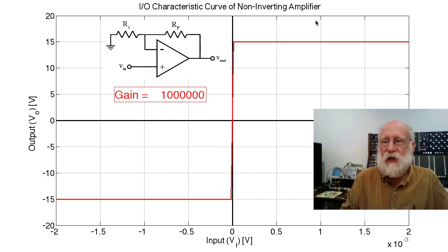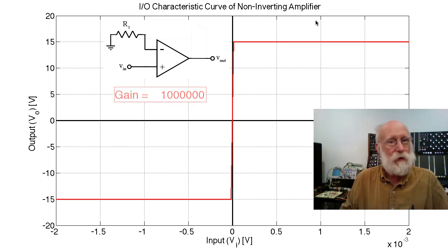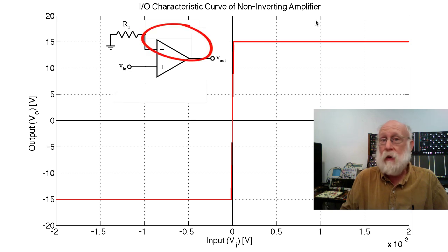If you were to continue this until the gain approached infinity, now that means that that feedback resistor approaches infinity, or you just pull it out altogether. There is no feedback resistor. There's where our no negative feedback comes in. You simply get rid of that feedback resistor.